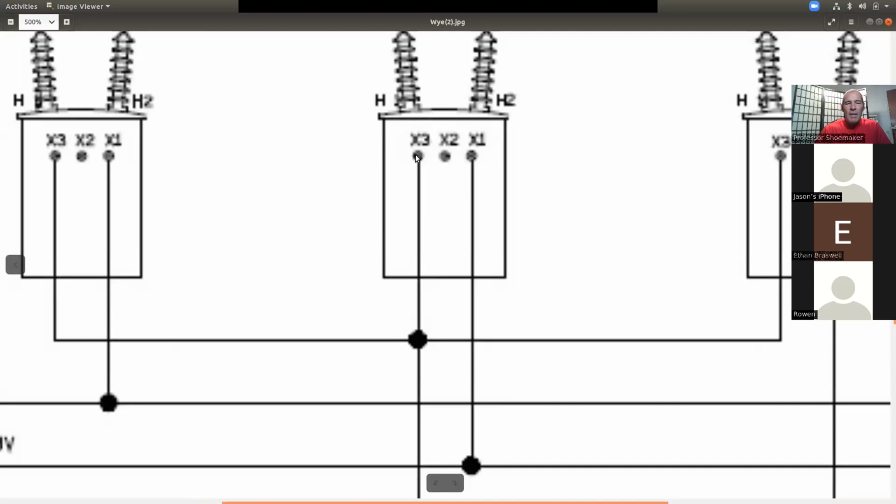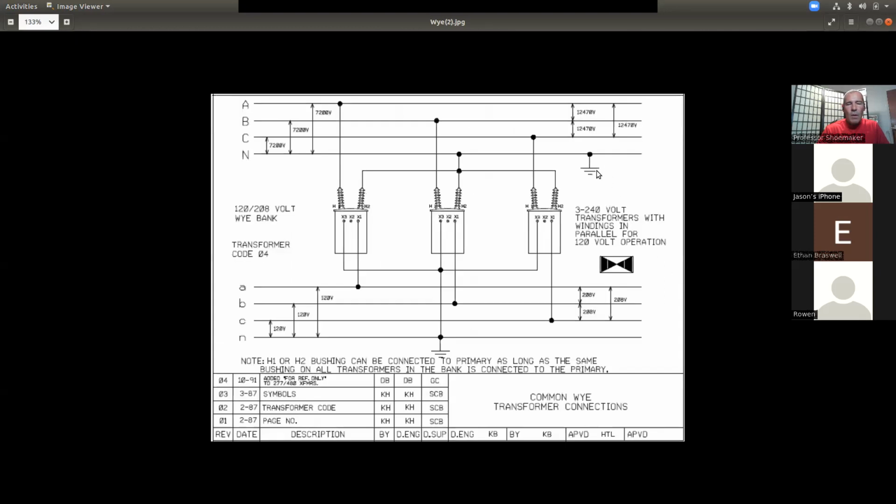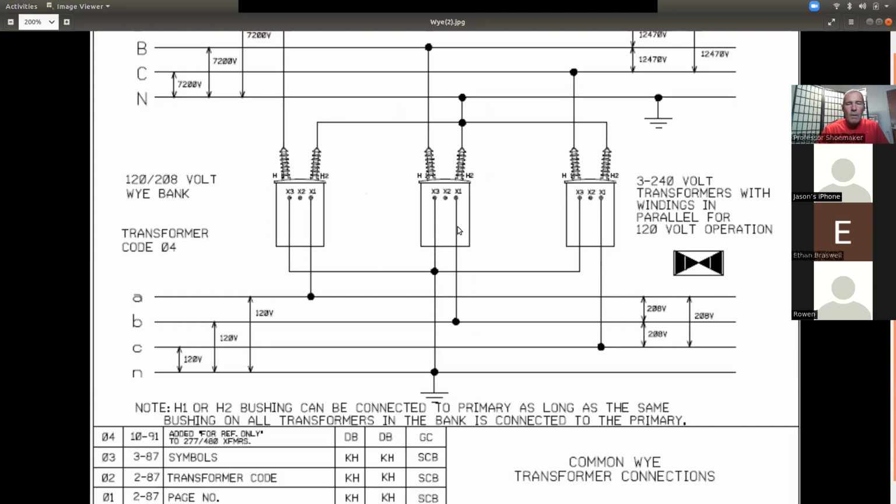AC leads, BD leads. That has to be done to all 3 transformers. Vitally important. And then that's just making that middle lug useless, right? It's empty. There are no leads going to it, so it's not used anymore.